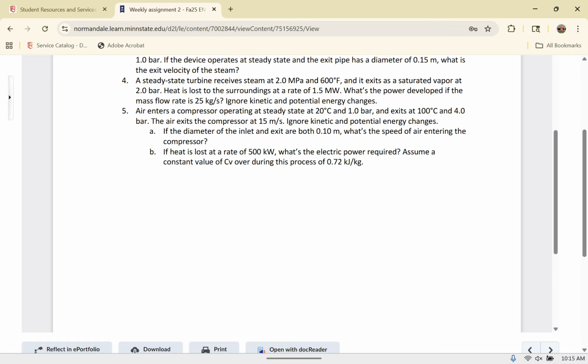I think the easiest way to think of it is if the system is gaining energy from work, it's negative. If the system is losing energy from work, it's positive. And it would be more than the heat loss because there's still energy being added, greater than the 500 kilowatts from that heat loss. Yeah, right. Any other questions?